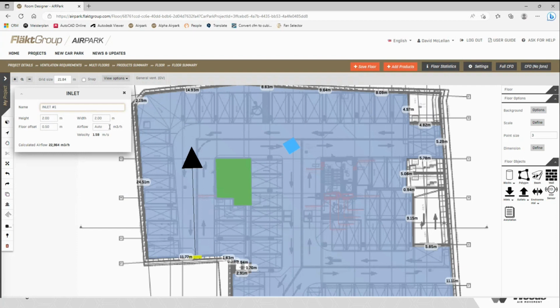With the airflow, the program will try and automatically create duties for you based on the ventilation settings you set up in that first page with all the presets. However, you can override this and insert whatever duties you particularly want for the boundary condition as well.